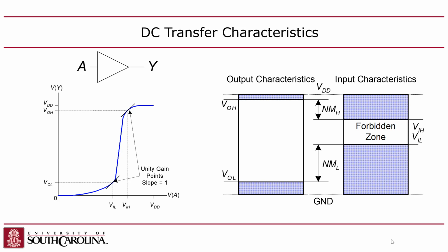There's also a noise margin for the high end, which is the same thing. You want to make sure you don't have noise on that wire that, when subtracted from VOH, brings it less than VIH, because of course the noise can add or subtract voltage.